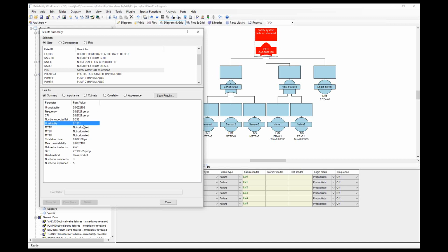An unreliability is about a 20% chance of experiencing a failure over the lifetime, which is a 10-year life. And we have other calculations for downtime. Unavailability, this one isn't relevant to this particular system. This is an aerospace measure, unavailability per flight hour. So we get a range of different results.